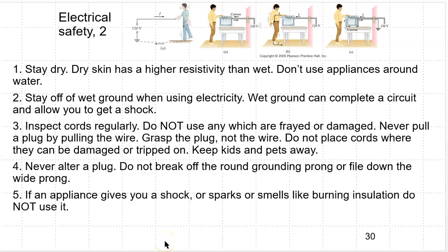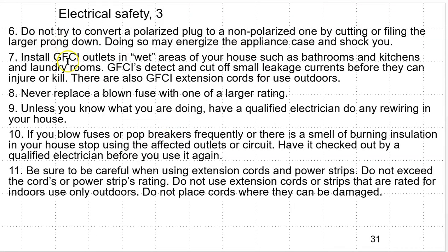Never alter a plug. Do not break off the round grounding prong or file down the wide prong. If an appliance gives you a shock or sparks or smells like burning insulation, don't use it. It's not worth your life. Do not try to convert a polarized plug to a non-polarized one by filing or cutting down the larger prong. Doing so may energize the appliance case and shock you.